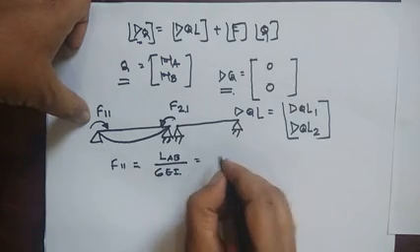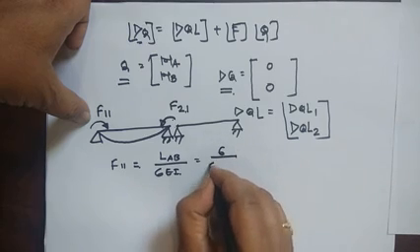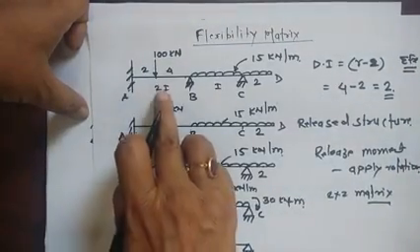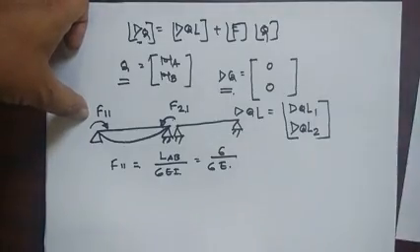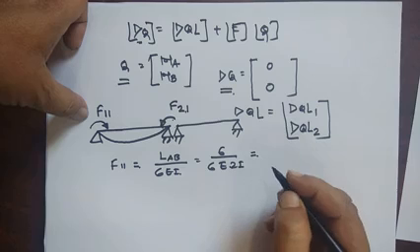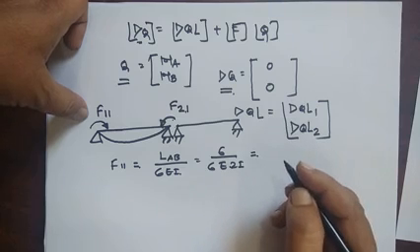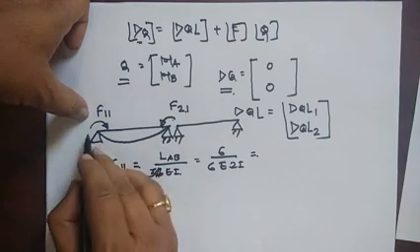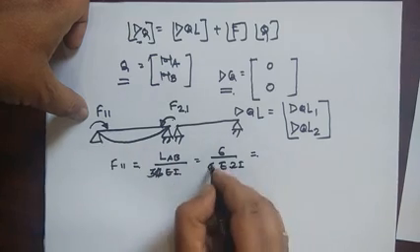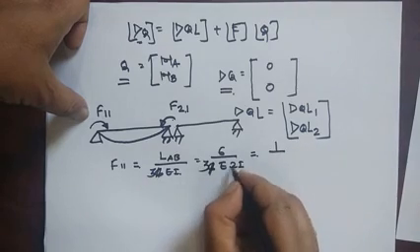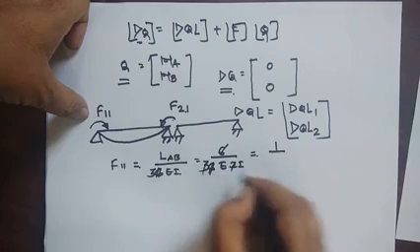So L is equal to 6E. Here in this case for this beam I is equal to 2I. So take here the 2I. So this becomes now, no, this is not 6, this is 3. Here we are applying rotation and development here. So this is not a 6, this is a 3. So this becomes the 1 by 3 into 2, 6 gets cancelled out. This is the EI.